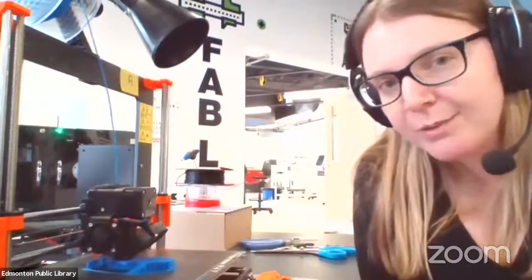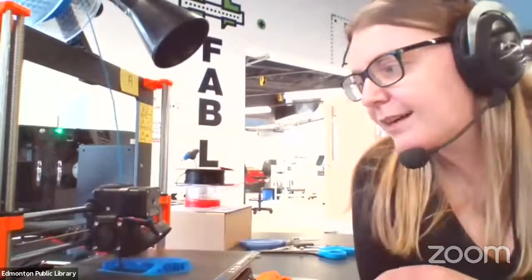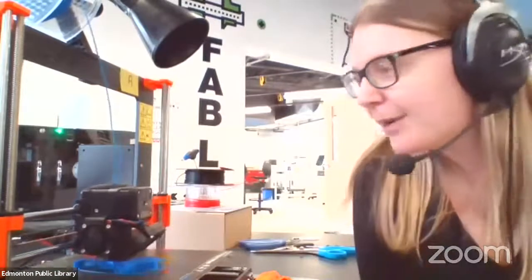So depending on what the project is and what people are trying to do with the 3D print afterwards, we might change the infill to make it denser, to make it lighter. We can also totally remove the infill if someone wants to make a hollow object or a vase. And that's a pretty popular thing. We've had people print vases before here at the library, and some really interesting patterns are possible even with Tinkercad. So yeah, that's a 3D print that's actually up and running.